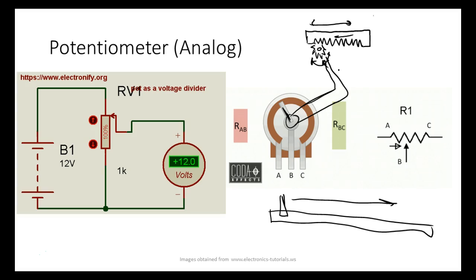Now we would have to scale it. We call it a transfer function. So we would have to scale it and say, okay, this many volts equals this many degrees. And so you'd have to do a little math. What most of your PLCs support now is a scale function. So you can bring it right in off these analog devices, and you can convert it to a binary number that represents that position. And we call that scaling, by the way.